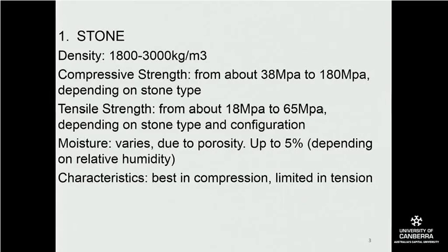Of course, the range has to do with the type of stone, whether it's a sedimentary stone or some sort of metamorphic or igneous stone, which we'll go through in a minute. Now, tensile strength is not very good at all, starting at about 18 megapascals and going through to 65 megapascals. So similar to unreinforced concrete. But of course, there's ways of getting around this, which I'll talk about in a minute.